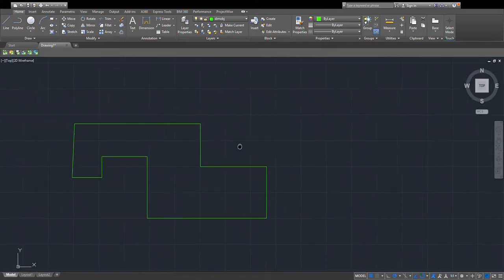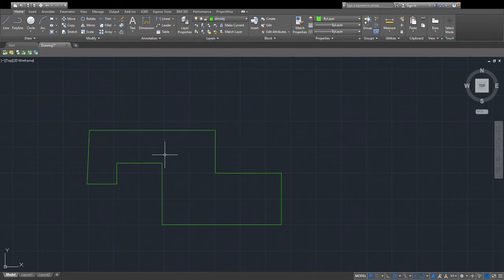Now I want to do some dimension lines. Let's say this was a building slab or a house slab, and I realize it's a little wonky here, and you wouldn't have a particular slab, but for learning purposes, it works. If I select the object, remember from our previous instruction that this is a polyline, so we can edit it by selecting it, and it brings up the grip edits. Any of these can be moved or changed.